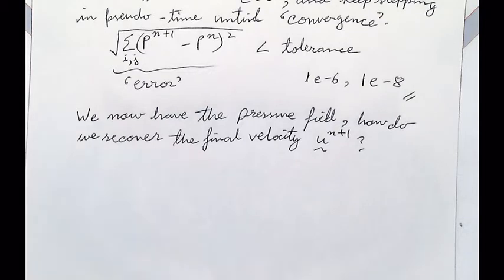So somebody was mentioning the energy equation. In incompressible flow, we don't solve the energy equation at all. It's decoupled. We are still discussing solving the Navier-Stokes equation.